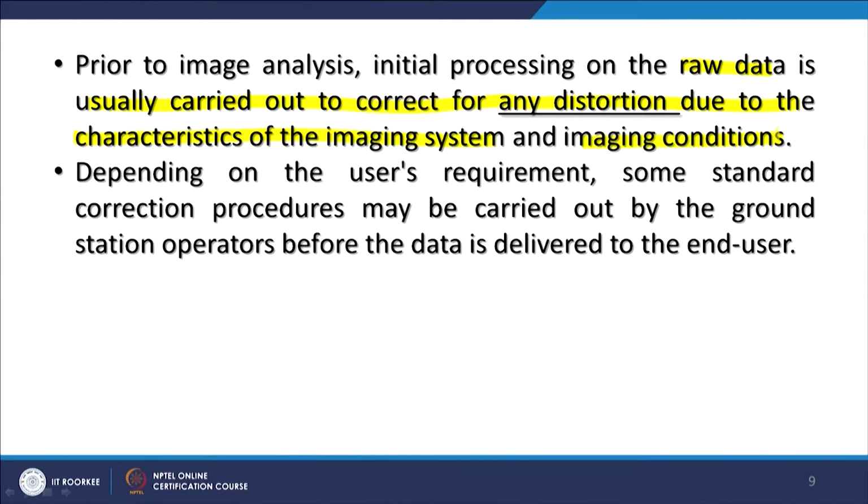And as I have mentioned, the first level of processing includes correcting the distortions which might have been caused by the imaging system. There might also be some issues related to calibrations of different CCDs. These are also called radiometric corrections. If that information is with the agency, they will first perform that correction and then the data will be uploaded on the server or supplied to the user.